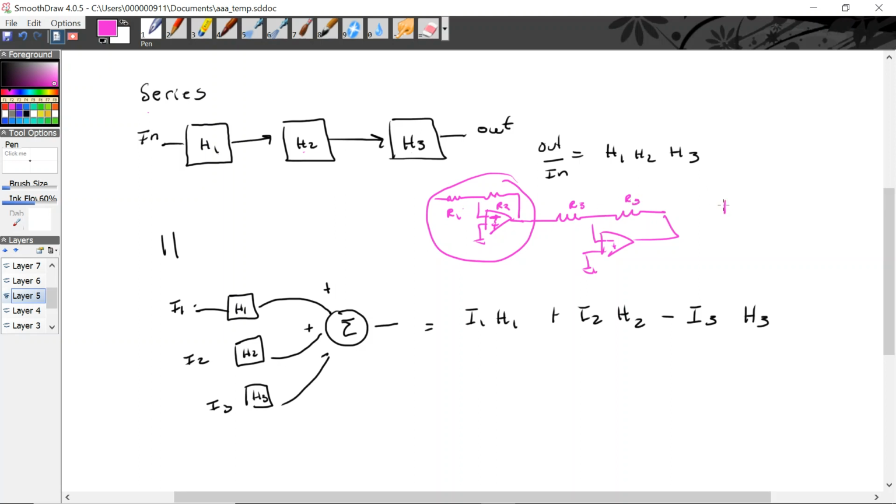So if I just put in some numbers, I basically get R2 over R1, R3, that should have been 4, and that should have been 3. Excuse me. So that would be the transfer function. Now, yeah, you can have filters in here. Anything that goes inside that you can have. But basically, just putting things in series, you know that these op-amps separate the circuits, if you will, so that you can get these discrete transfer functions.